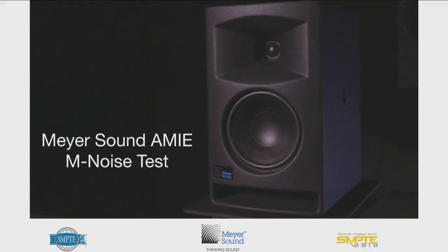The beginning of our procedure is you take a guess of a signal level that the speaker can reproduce. You measure that and store it, and then you turn it up 3 dB and see if it's the same. If it's the same, then you were right, and the speaker is reproducing that linearly, and then you can proceed to turn it up even more until it shows some nonlinear behavior. So that's what we're going to show here.